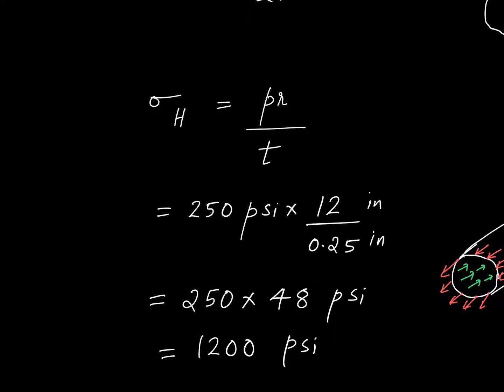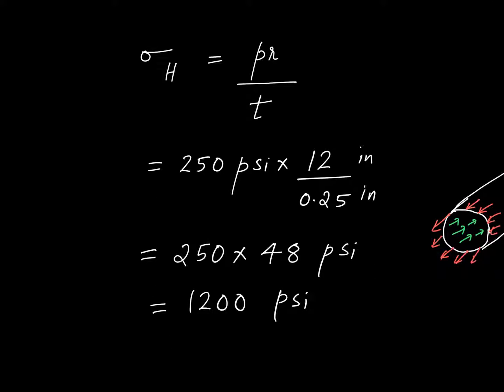Sorry, there won't be any longitudinal stress, but there will be circumferential stress, which is given by this particular formula, PR by T. This formula holds true because your pressure vessel is a thin-wall pressure vessel, where the R by T ratio is on the order of 40. Make sense? So the rest of the things are simply plug and check. All quantities are given to you.